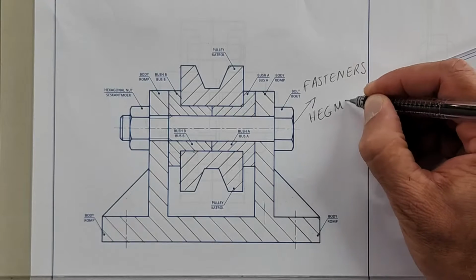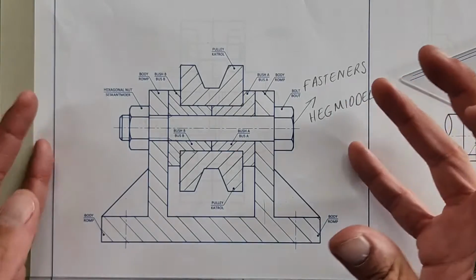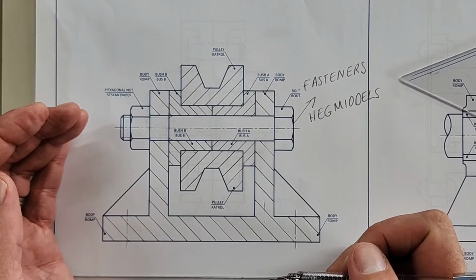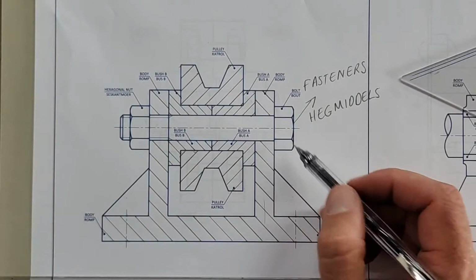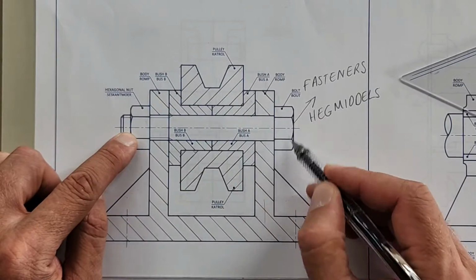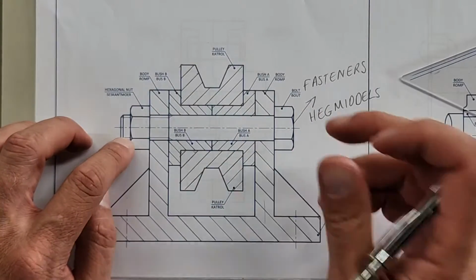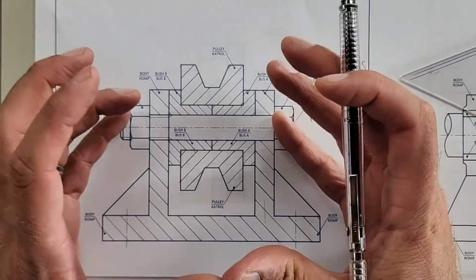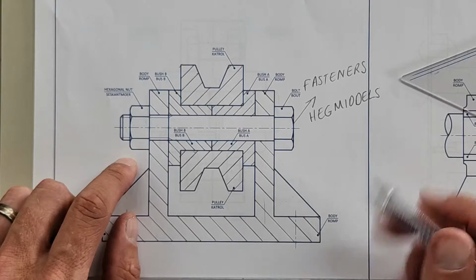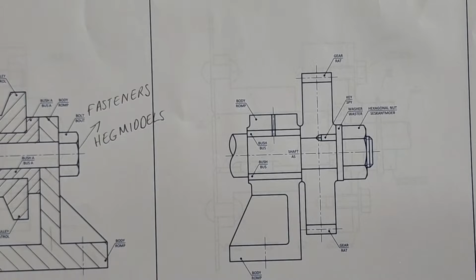Okay? Hegmiddels in Afrikaans. Hechtings of hegmiddels. Okay? Here's the rule. Anything that is used to join something together is never sectioned. Hoor julle my? Enigiets wat as 'n hegmiddel gebruik word in hierdie voorwerp word nooit gearseer nie. Nie 'n skag nie, nie 'n boutkop nie, nie 'n moer nie, nie 'n wasser nie, nie 'n klinknaal nie, not a crab screw, nothing. Nothing that's used to join things together is going to have a cutting plane sectioning through it. Happy? Any questions on this first example? Alright, let's move on to the second one. We're going to pick up some speed here.